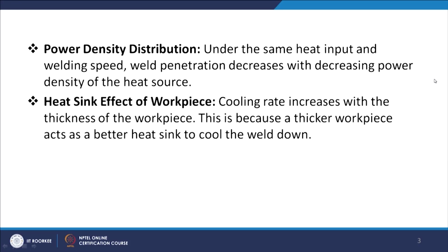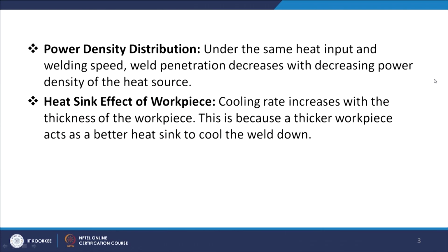The workpiece basically works as a heat sink, because the heat which is generated is being taken away by the workpiece itself. So, as you increase the thickness of the workpiece, it will act as a better heat sink to cool the weld down.